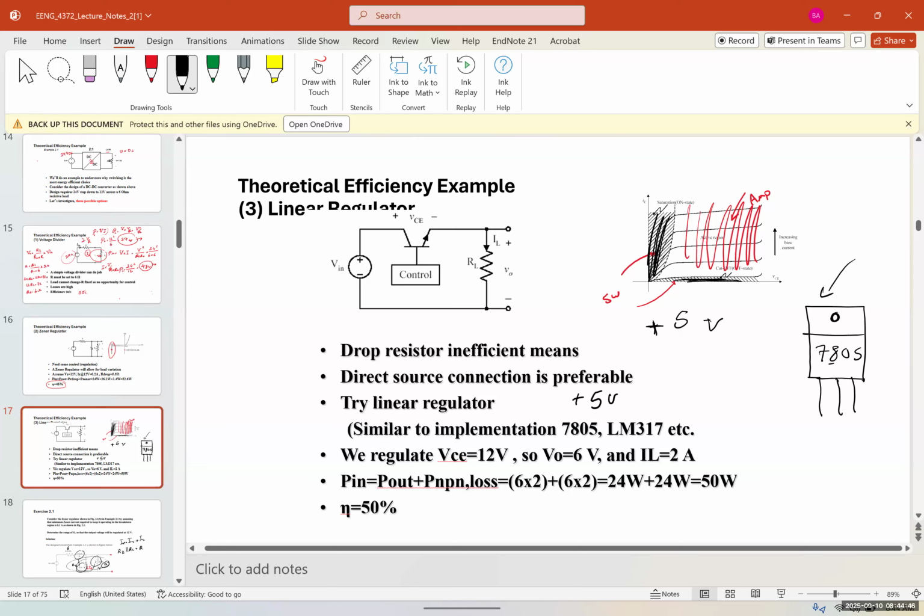Okay, so in the lab we did a part, and this was your final project if you recall, that we built a rectifier, and in those rectifiers what we use is a voltage regulator. A voltage regulator is an element built of a couple transistors, and it regulates the output voltage. So regardless of the input voltage, you're gonna have a fixed voltage in the output.